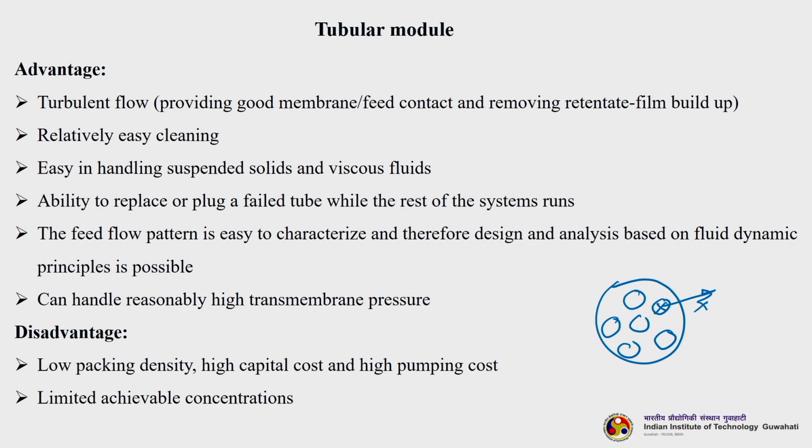Feed flow pattern is easy to characterize, and therefore design and analysis based on fluid dynamics principles is also possible, and it can handle reasonably high transmembrane pressure. Of course, if you use ceramic membranes, then it can withstand more transmembrane pressure. However, the disadvantage is low packing density, that is, the membrane area per volume is less, capital cost is a little high, and the pumping cost required to pump the feed is also relatively higher than other modules.